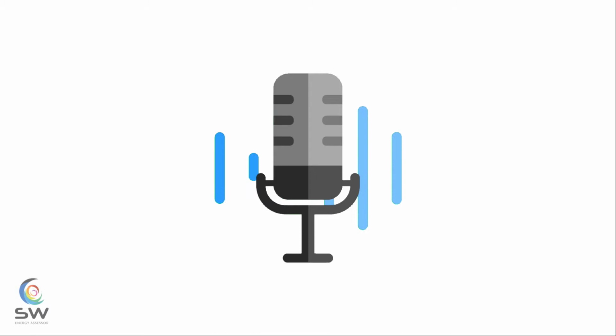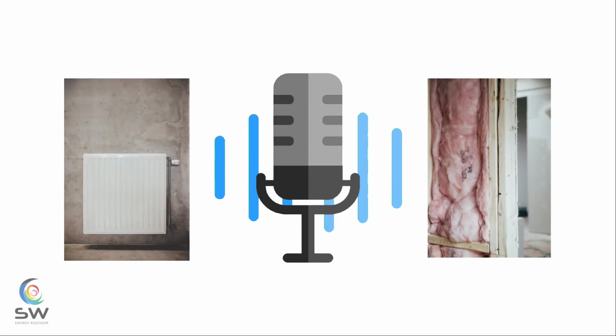In this video, we outline the SAP calculation process. Why do you need one? A SAP calculation looks at the thermal and heating efficiency of your proposed dwelling in line with approved document Part L1A. In this document, it sets out the targets you must meet for your dwelling. It looks at your insulation levels and your heating system against the targets set out within the document.